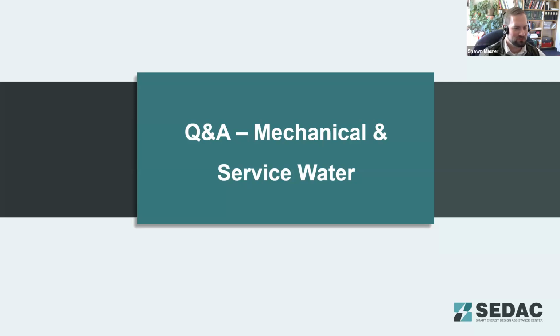That wraps up all our section questions on lighting and controls and things that we wanted to cover. So we'll start moving into mechanical and service water systems. And for that sign, all we're recognizing is that it needs to be part of your exterior lighting power calculation. And it says you need to reduce it by at least 50%. So you could include the sign as part of the 50% you leave on, or you can include it as part of the 50% you turn off. Either way, but it all gets lumped together there as one thing.